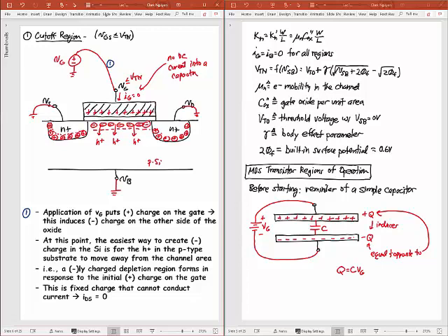Right? So I have this depletion region on the N plus side very thin. And those will be positively charged, but on the P side, because it's less heavily doped than the N plus, this is going to be a thicker depletion region. So I can sort of draw it like this. And this will come in and connect with this depletion region right there.